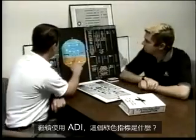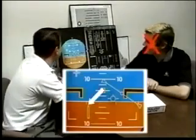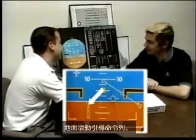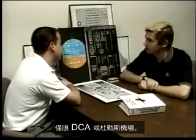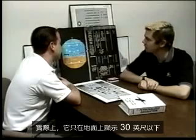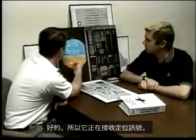Staying with the ADI, what's this green pointer? That's called the Washington Monument. Let's be more specific. That's the Ground Roll Guidance Command Bar. Is that always displayed? No, only in DCA or Dulles. Actually, it's displayed only on the ground up to 30 feet during a landing or a takeoff on a runway with a localizer. Okay, so it's receiving a localizer signal.